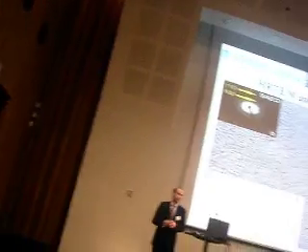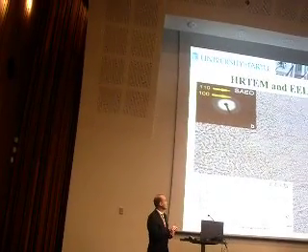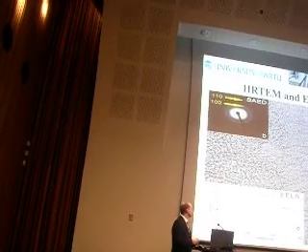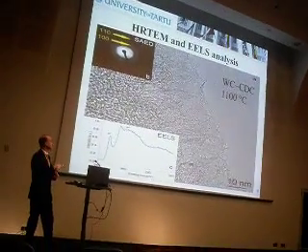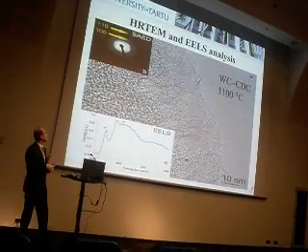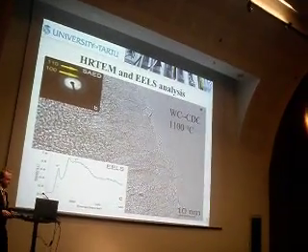But however, when we look at the material that was synthesized at 1100 degrees, we can see some partly graphitized material. It's still mostly amorphous, but nonetheless we can see certain elements of graphitization. And also from the selected area electron diffraction, we can already see the rings that correspond to graphite.